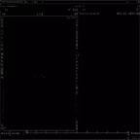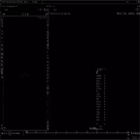I want to get rid of the parameters view, just to have more space for the network editor. But of course I need the parameters. If I lay down a GeoNode at the moment, I don't have any parameters shown. But if I hover over the network view and press P, I get this overlay pane that uses less space than the parameters window, but displays the same parameters. So for today, I prefer this view.